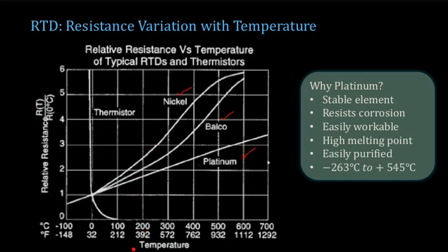You can see that once the temperature varies, the resistance is increasing, and the most commonly used metal is platinum, because it has a linear relationship between temperature and resistance. Others also have a linear relationship, but only in a very small range. If you take the case of nickel, it has a linear relationship somewhere in this range, from 0 degree up to say 300 degree Celsius.